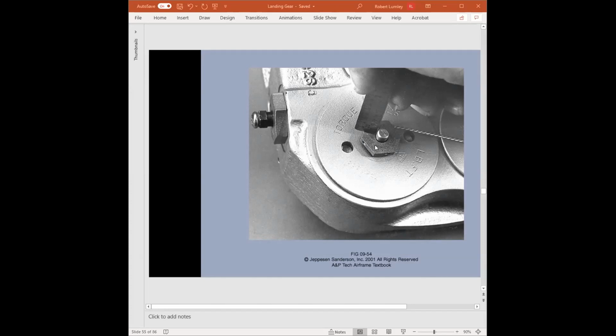The important part about this is, let's say we have to replace the pads, right? Well, if anybody ever replaced the brake pads on your car, you know that you have to push the pistons back into the caliper so that the pads can go in and there will be enough clearance. The same thing is true here. The only problem is the grip collar would not let the pin move outward or back into the caliper.